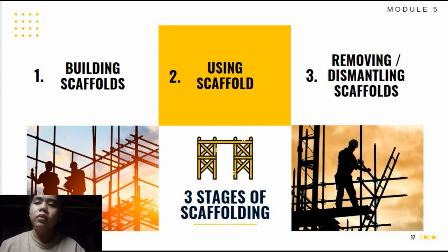Under job site rules, put in writing and teach to all employees as part of the safety culture. Scaffold inspection: a competent person inspects scaffold for visible defects before each shift and after any alteration.